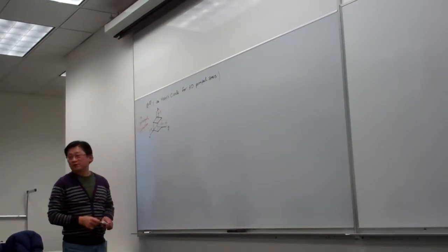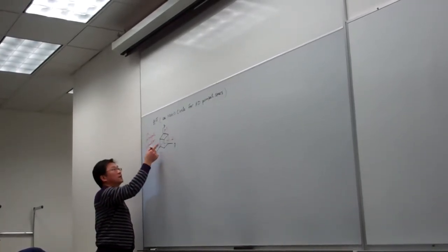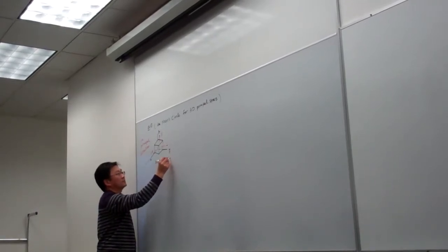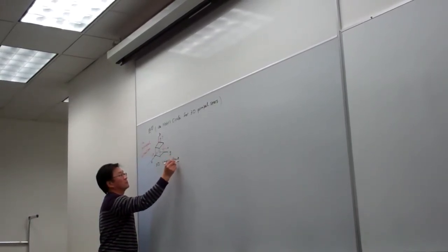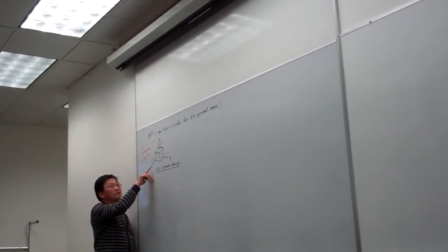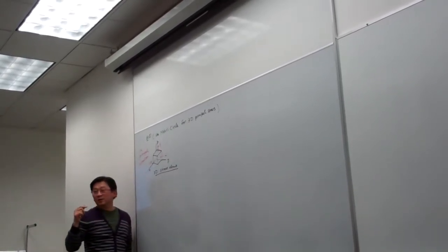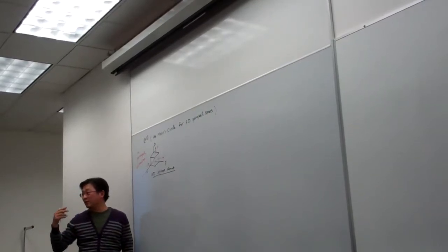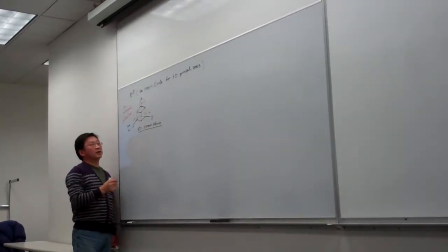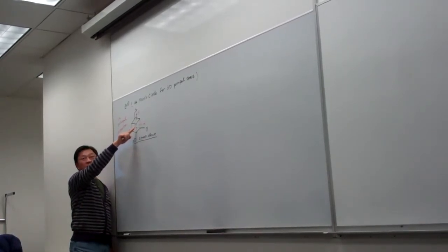So the way we draw the Mohr circles is this. We simply look at this. This is a 3D stress element. From the viewpoint in each direction, what we see in front of us will be a projection, a plane. If you imagine you are a small guy, for example, sitting on the x-axis, looking into this element.